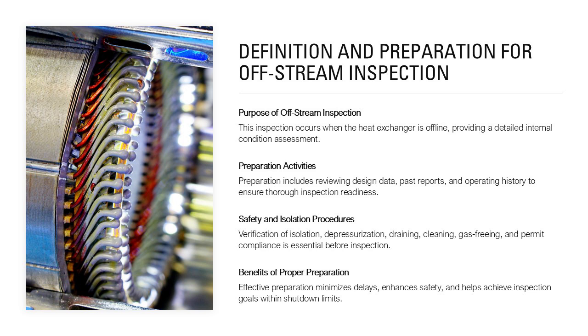Preparation is critical and includes reviewing design data, previous inspection reports, and operating history. Proper isolation, depressurization, draining, cleaning, and gas freeing must be verified before entry or opening. Inspectors should ensure that blinds are installed as required and that permits and safety procedures are in place.